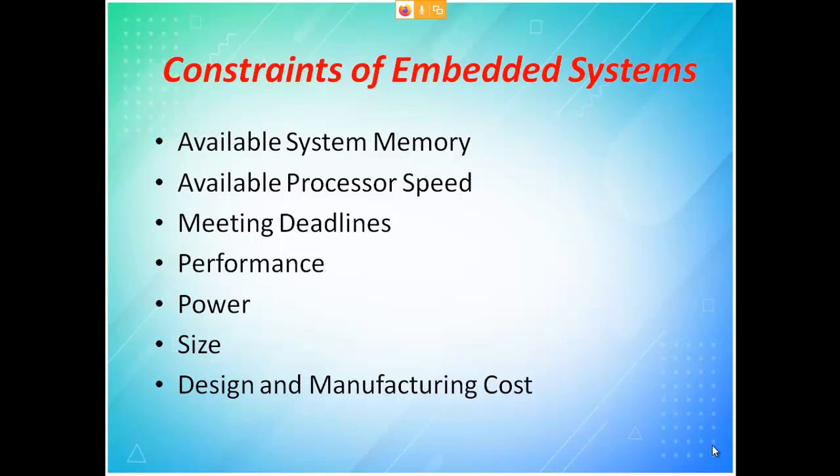You might have studied the 8085 with a 5 volt VCC. If I want to reduce the power consumption of the processor, I have to bring the voltage down. That is why nowadays microcontrollers and processors are available at 3.3 volts, and some even with a 1.5 volt power supply. So that is with respect to power.